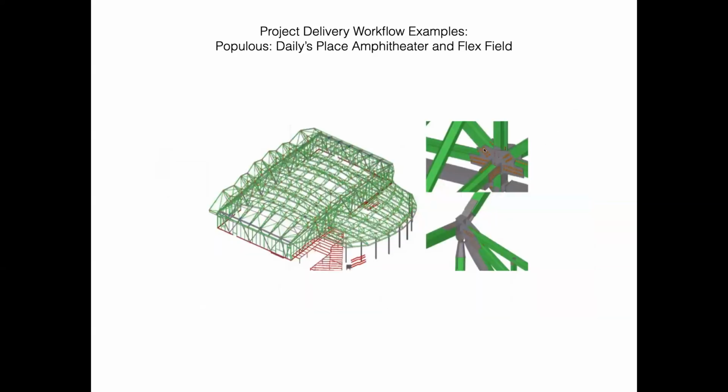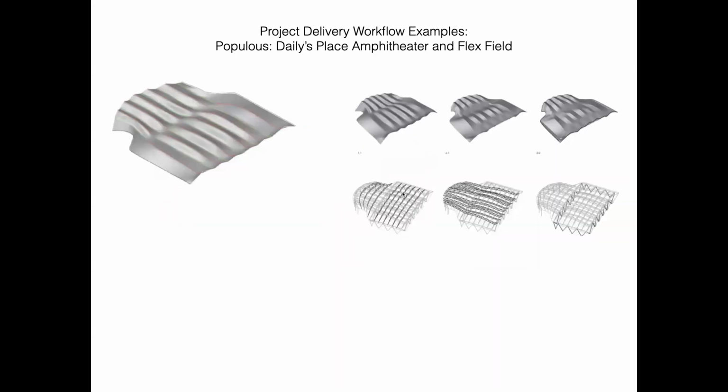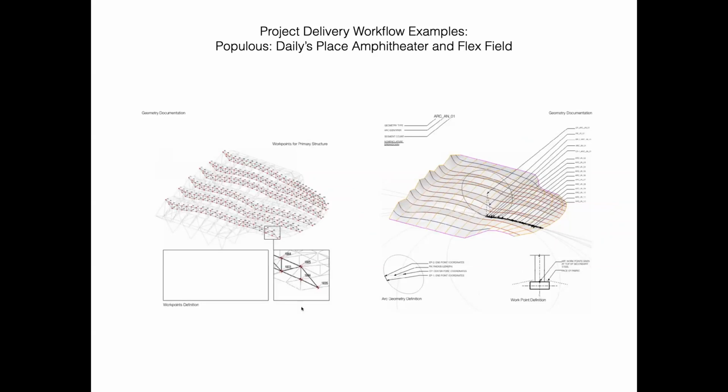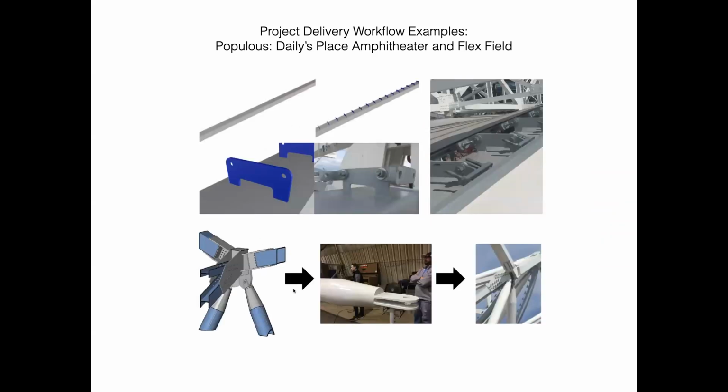And then from there they get detailed, right? And so you take something from, let's say, Grasshopper that the architect is developing, you take it into Pro Engineer or CATIA or SolidWorks or whatever the engineers are using, right? And then that gets taken out into Tekla or some other software that the steel industry uses in order to develop literally every single plate and bolt and nut, right? So every single detail is designed and engineered. Every single thing that's welded, every bolt, every piece of hardware.